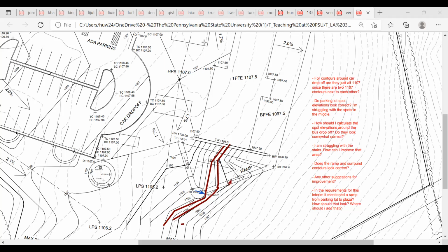Then this would, you turn it so it will drain outside. The side slope will create this water flow, okay? Yeah, we're creating a swale over here toward the wall, and that's not recommended. So this will be doing that.